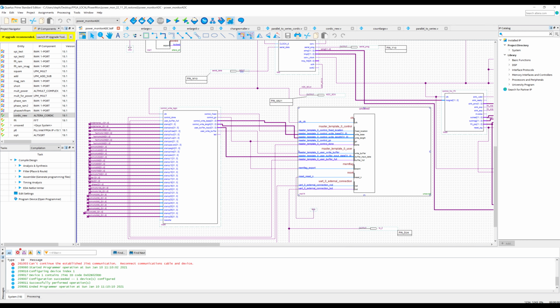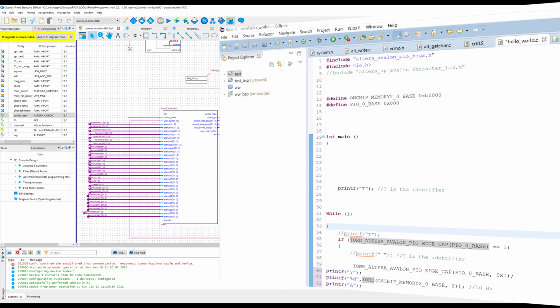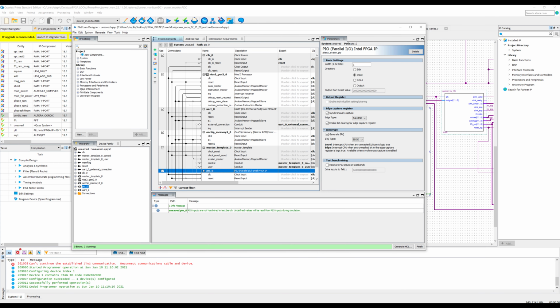I can show you in the code here that the PIO flag is this one here, and that's coming in from this variable called control go. So every time we have a burst of data to write into the memory scope of the embedded processor, we will make this control go a one clock cycle flag to tell the software that we have something, do something. So that's the embedded processor. Not much to it really.